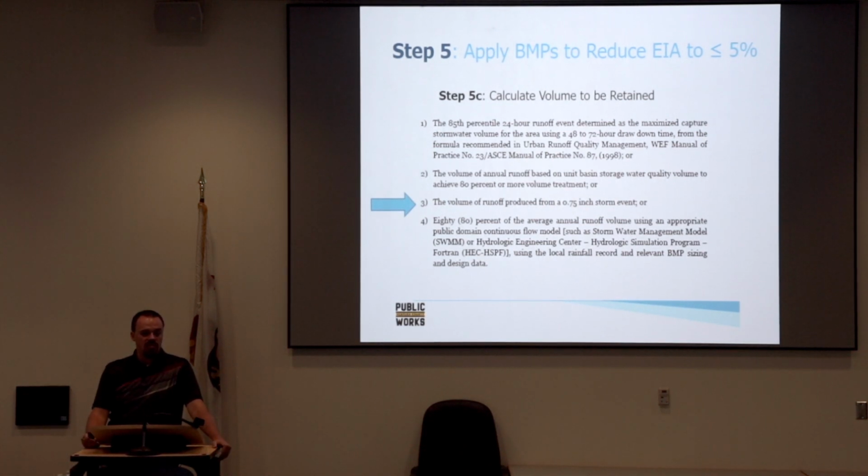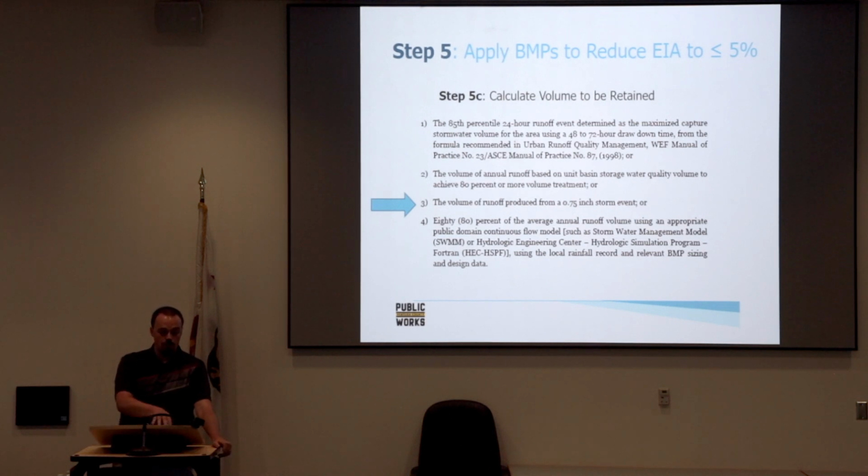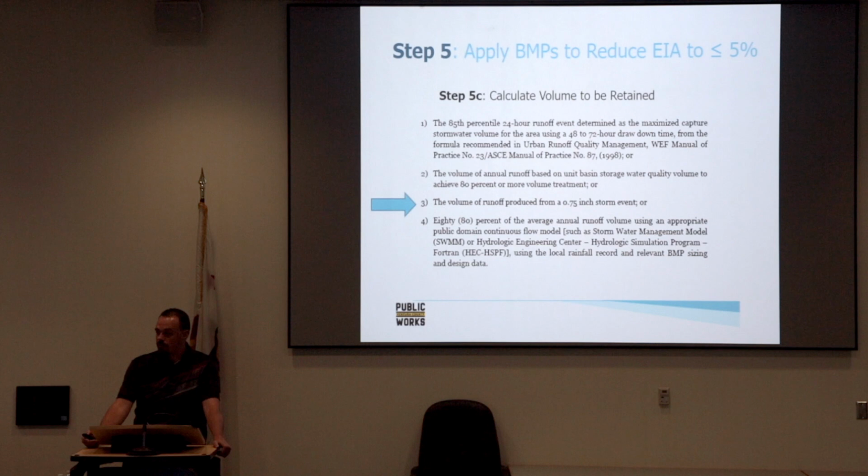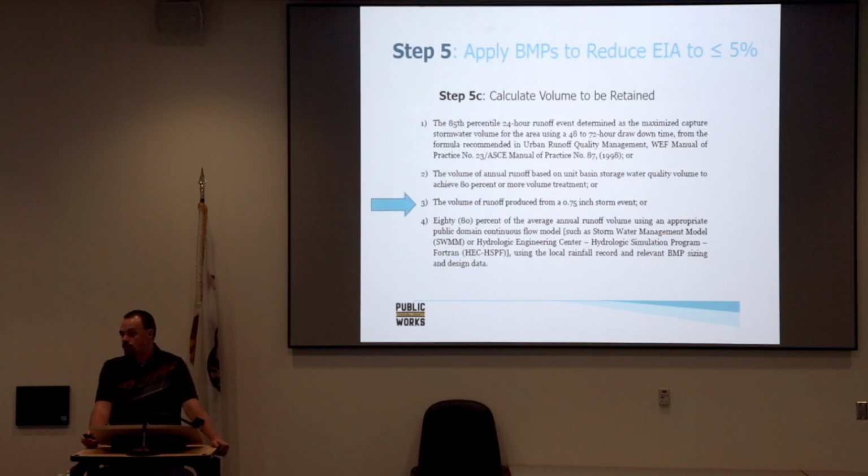Again, I think it's going to the same assumption that rainfall is the same everywhere. They want people to be more realistic with what their BMPs are actually going to be sized. But for the sake of the example that I'm going through and the BMPs here, we're just going to use the 0.75 inches. I haven't had an issue myself with accepting the 0.75 inches if a project's even over an acre. Generally, the reasoning for that is if the project's over 5 acres, they have to do some fairly significant detention to meet grading requirements for the pre and post effluent requirements. So as part of that, the basins are generally much more oversized than they need to be. But I do make a point to comment on that when necessary.